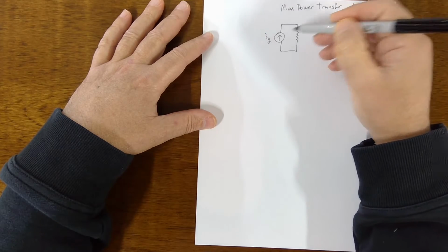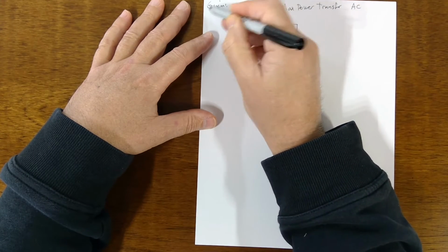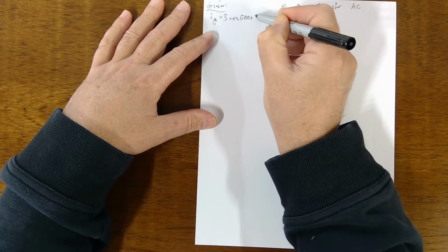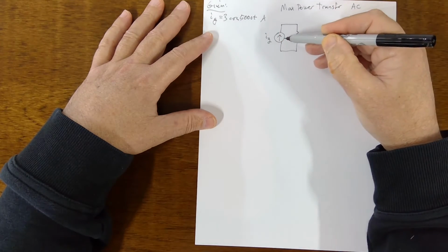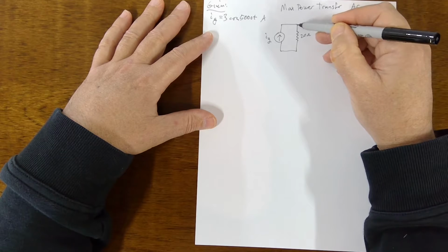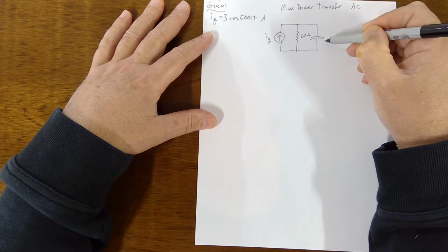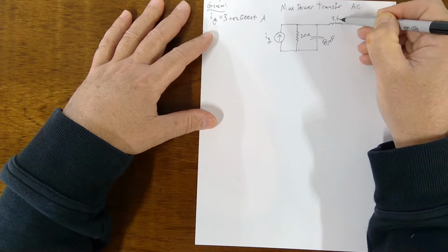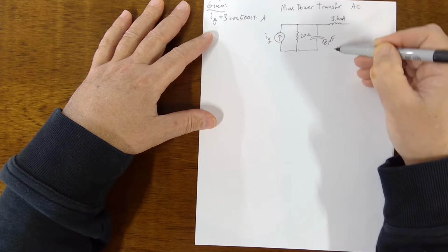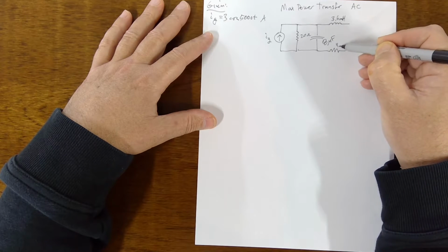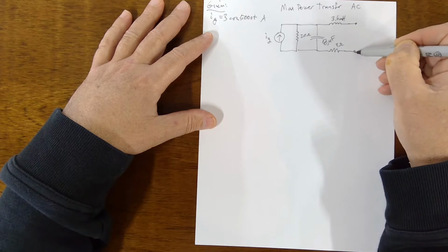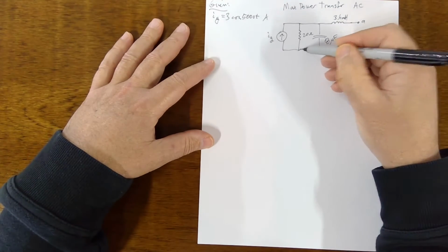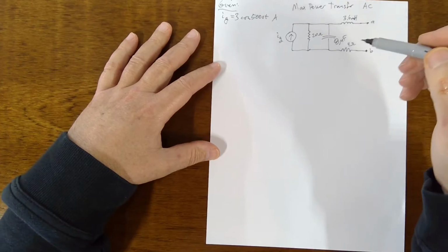So we've got a sinusoidal source, I sub g, given by 3 cosine 5000t in amps. That's this guy, I sub g, and there's a 20 ohm resistor. There's an 8 microfarad cap. There's an inductor up here, 3.6 millihenries, and another resistor, 4 ohm over here. Then we've got these terminals A, B. We're going to connect a load across A, B. We haven't done that since chapter 4, but we're going to do that.